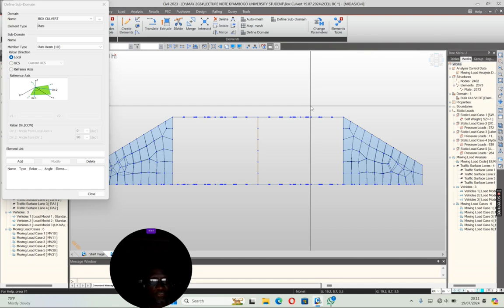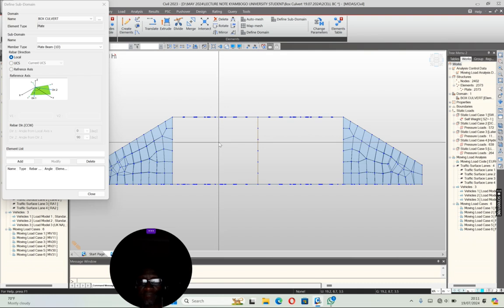I could, for demonstration, only highlight the entire slab as one member, but it's also good to do what is realistic. So I would do the hogging moment area and bending moment area as two separate ones. I'm going to divide this so that the first part, these two from the external wall, will be one member.